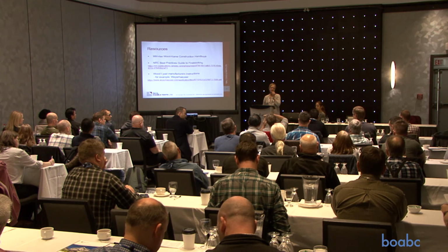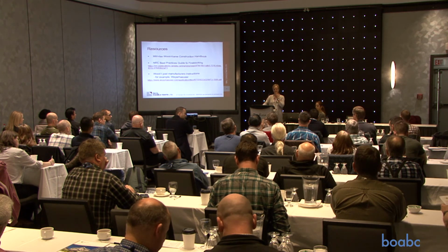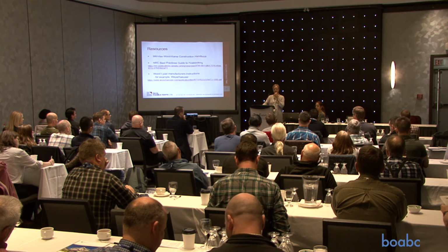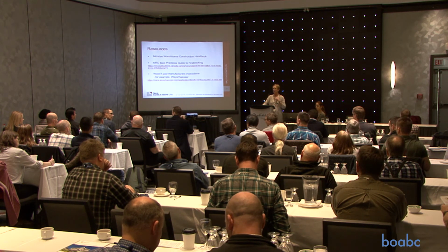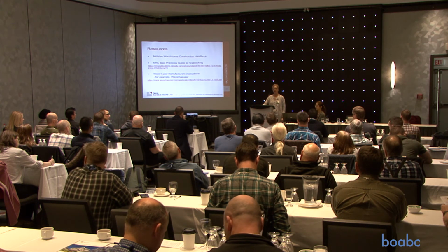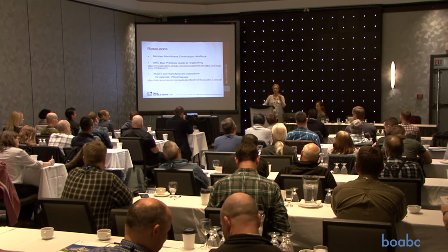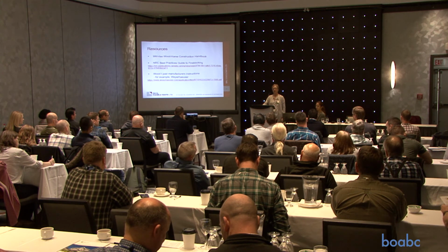Does it drop it down enough that you're not on the plate anymore? No, you're still on the top plate. But given the fact that that joint, especially the single joint, is your failure, now you've got that single joint dropped down a little bit, and you're only relying on that. So you have no backing. Yeah. If you have a piece of Resilient bar either way, that ceiling drywall still abuts the top plate. No gap there. You've just moved the joint down a little bit.